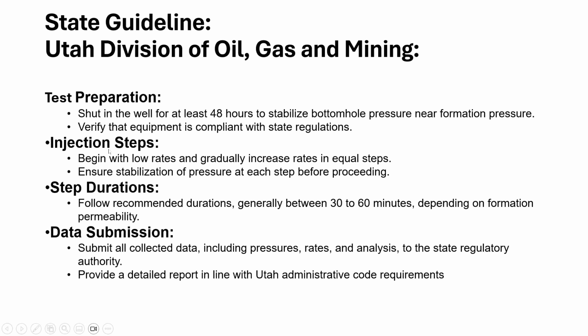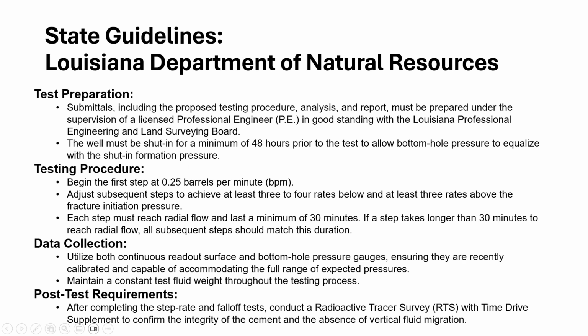Ensure stabilization of pressure at each step. Follow recommended guidelines for the 30 to 60-minute decision, and again, it depends on formation permeability. And you submit all data, including the pressure, rates, and your analysis, to the regulatory body. Louisiana is very thorough with theirs.